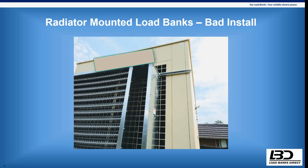Now, a lot of the smaller generator sets, let's say 250 kW and below, are not put into a custom walk-in enclosure. It's a factory enclosure where there's not room to have that side contactor box. There's not room to wedge a load bank inside there. So I think Eric's going to talk to you about some roof-mounted solutions that might be better than trying to couple it directly to the radiator, like somebody tried to do here in this installation.